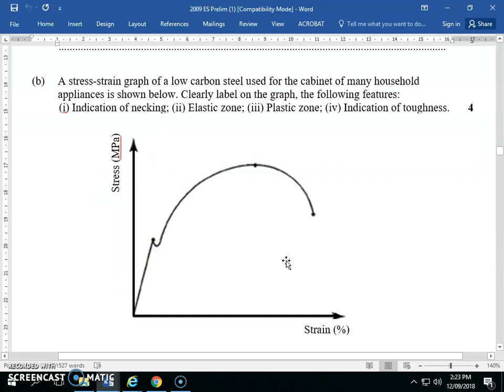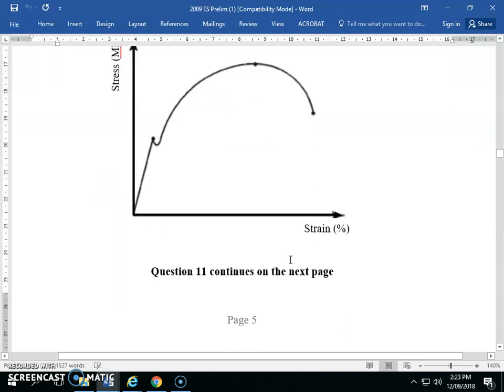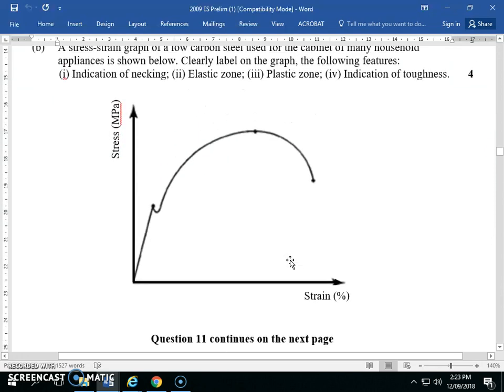Starts with a D. Ductile. Great. Yes. Typically, 0.3% steel is something we use so often that you should recognize that curve. For other things like really low carbon or brass, we get more of a progressive yield. We don't have the definite yield point. For high carbon, we're more likely to have